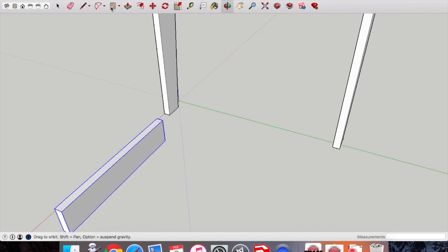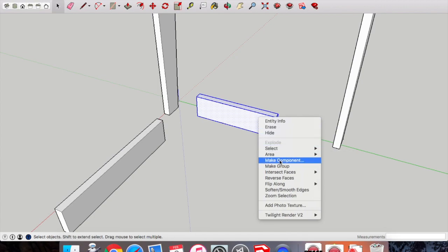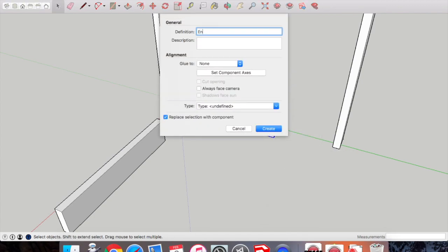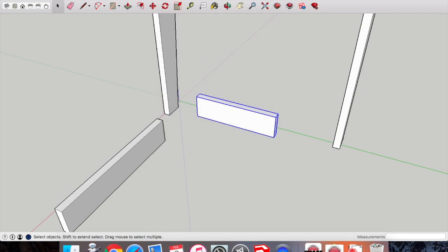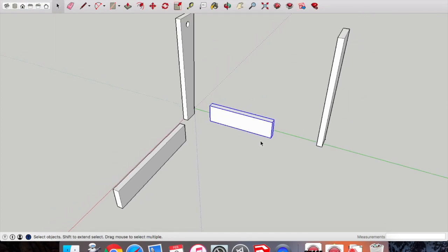Now we're going to draw the end in, basically the same steps. This time we're going to enter in 19, 250, because we drew it on that different axis there, and push pull up 70 and press enter. So the main thing there is we started with 19. You can still type in the dimensions the other way, it just means you need to rotate it. Same thing there, make it a component, call it the end.